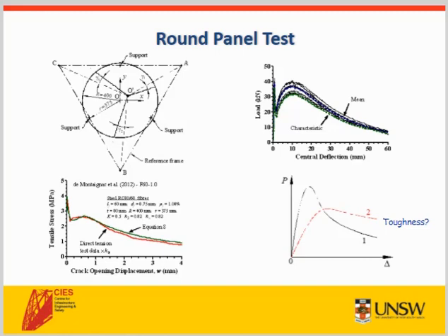However, over the last decade or so, design methodologies have moved from defining the post-cracking strength of fibre-reinforced concrete from the area under the load versus displacement curve to defining the toughness of fibre-reinforced concrete in terms of the residual tensile strength resisted by specimens at various stages of the test. Consider, for example, the response of the curves on the bottom right of screen. Both curves give the same area under the curve, but clearly have different responses.